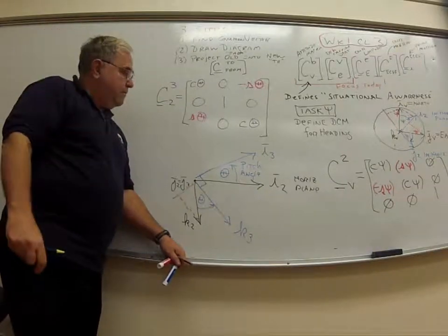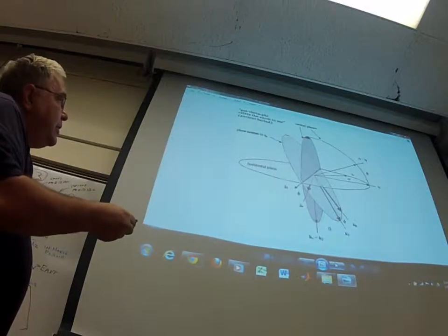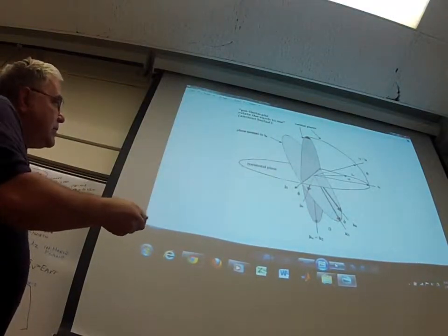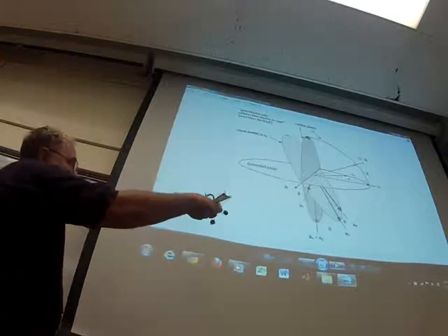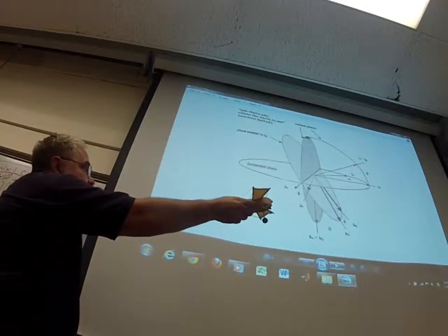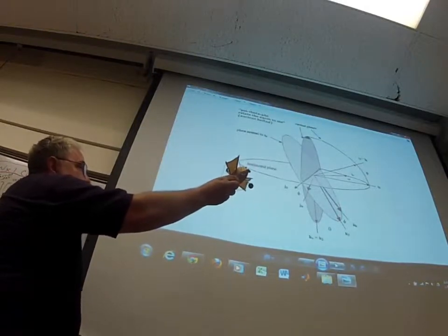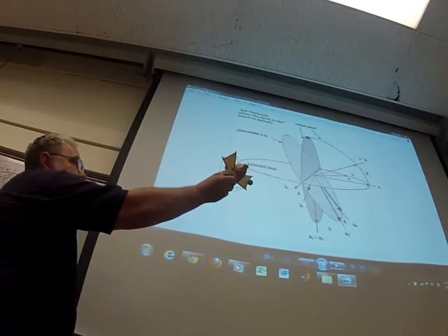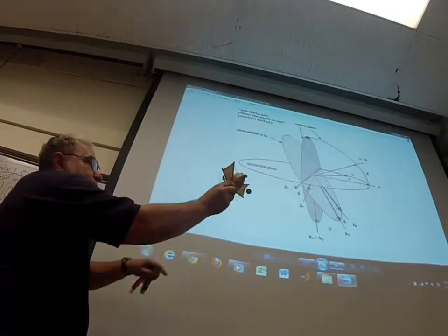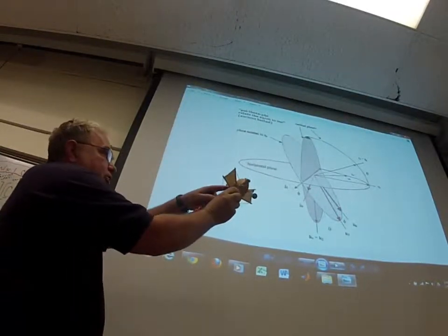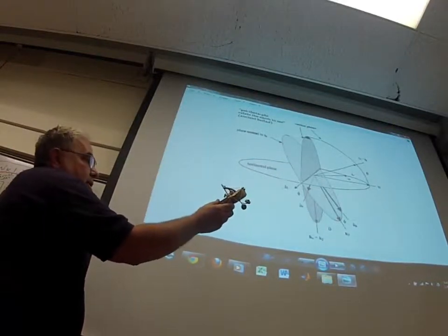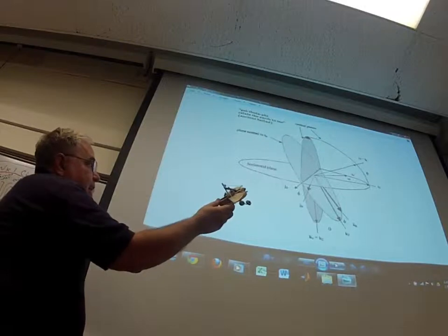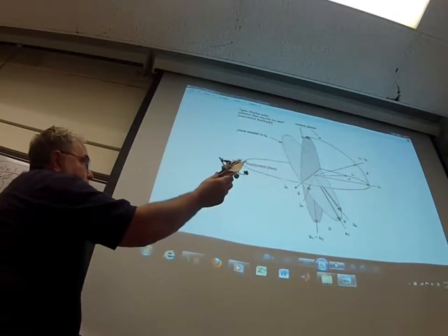Okay. The third rotation is going to be about IB, which I can't get to show on it. So the aircraft has gone in the horizontal plane, the heading, it's rotated up to IB, and then the IB axis will rotate the wings. The J2 of the wings will become JB of the actual wing. J3 will become actually JB, the right wing, and the aircraft will have this arbitrary attitude.